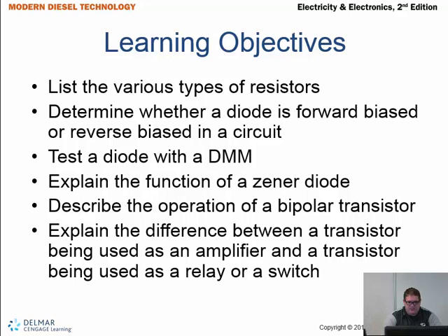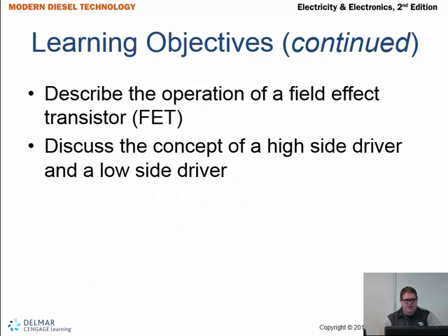Explain the difference between a transistor being used as an amplifier and a transistor being used as a switch, and what that means. Describe the operation of a field effect transistor, or a FET. You're going to hear that term a lot on the diesel side of the house. Maybe not quite as much on the automotive side, but I think this is becoming a more popular term. Instead of calling it a fuse inside the module, we're talking about what it actually is, which is a field effect transistor. And we'll discuss the concept of a high side driver and a low side driver.